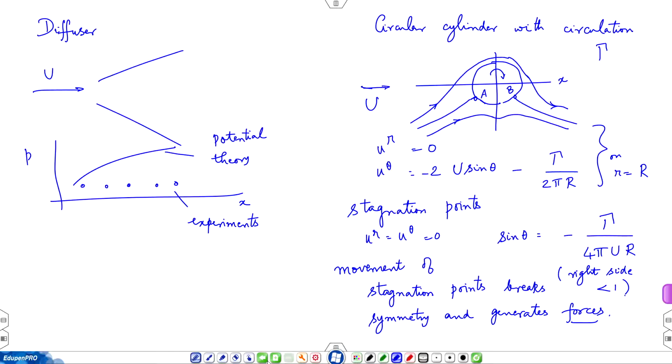One of them says, I have a circular cylinder rotating at some angular speed, maybe 100 RPM, and then it is placed in an air stream with a velocity of 1 meter per second. What will be the lift generated by this arrangement? How much is the lift? It's just rho u gamma, except that you have to relate, u is 1 meter per second, relate gamma to omega.